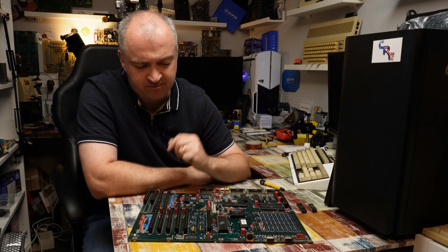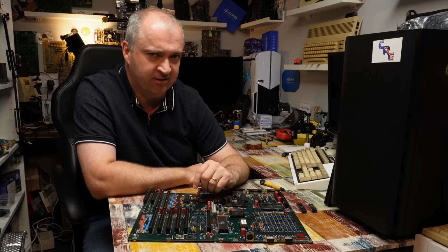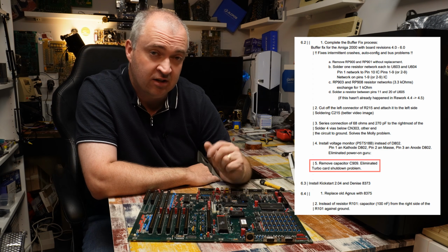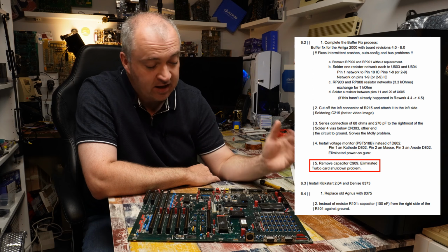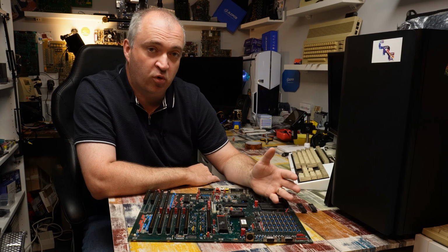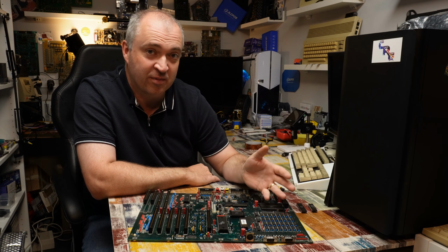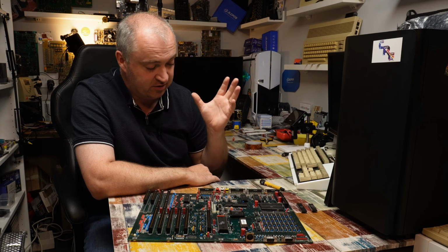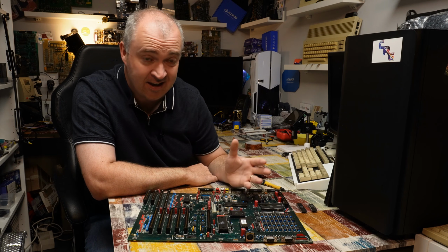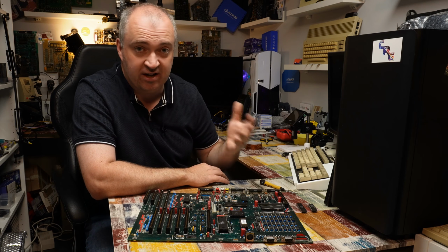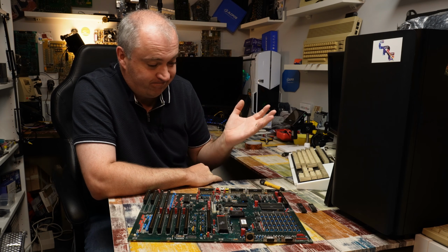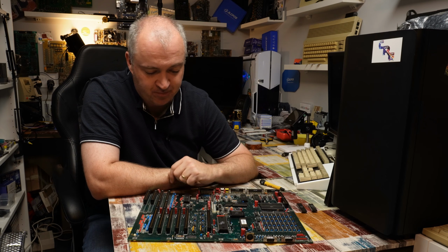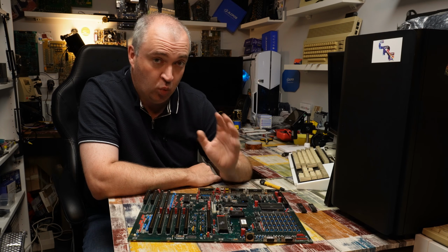Now, I know you're going to say, Glenn, there was more stuff on that list. And yes, there was. But the next item was to remove a capacitor at position C909. I have been over every square inch of this board twice. I cannot find that capacitor. So it's either not on a 4.4 and was maybe just fitted to a 6.2 by mistake, and then the engineering notes tell you to remove it, or I'm just going blind and can't find it. So if anyone knows better, maybe let me know. If C909 is on this board, where is it?